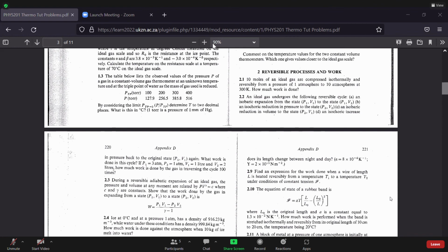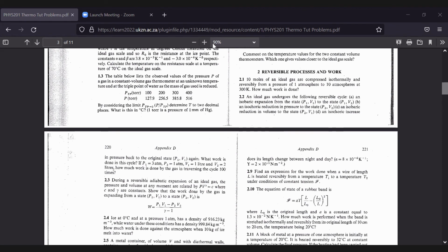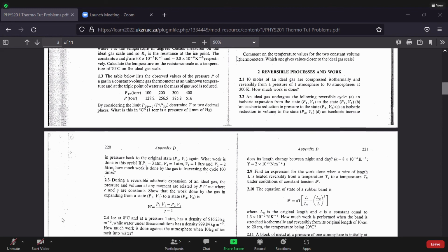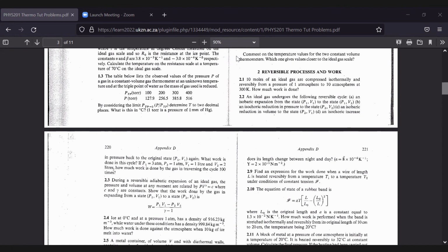Where did you get that formula from? I haven't seen that before. Where's that from? Online. No, I've never seen that before. Which kind of process is that for? Did they say if it was isothermal or isobaric or anything? For the entire work done? No. So if you want to find the entire work done, you need to do those integrals along each part.